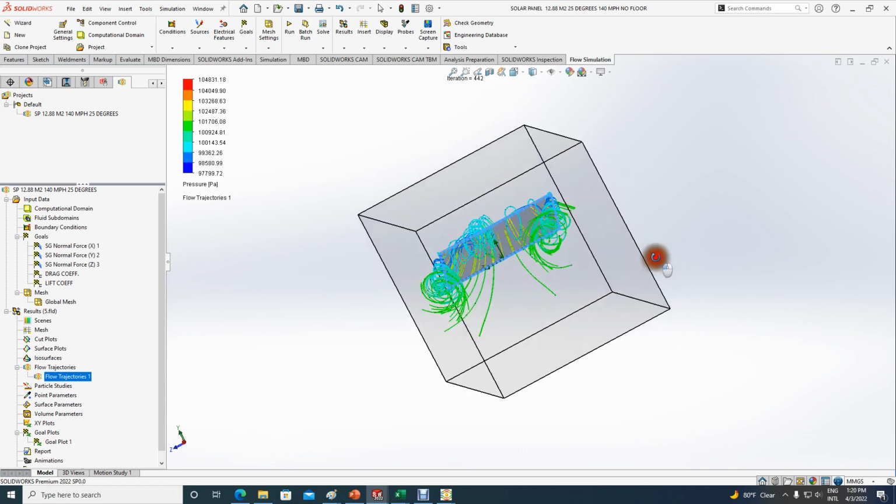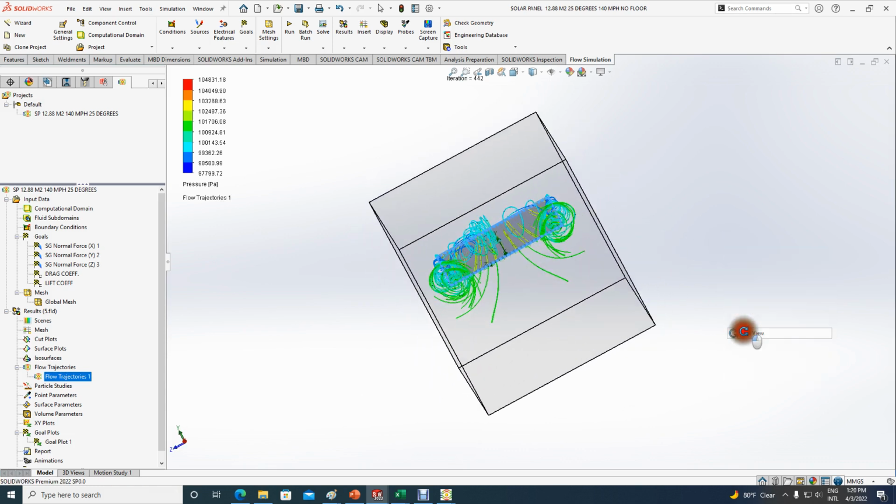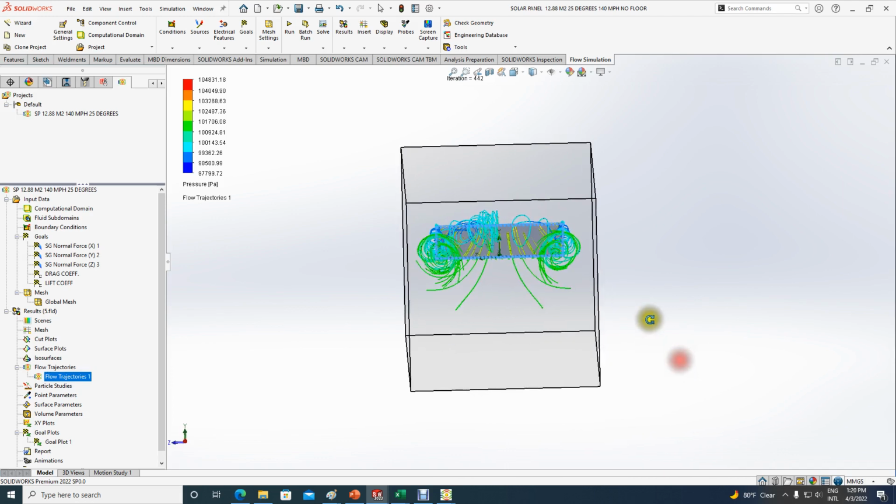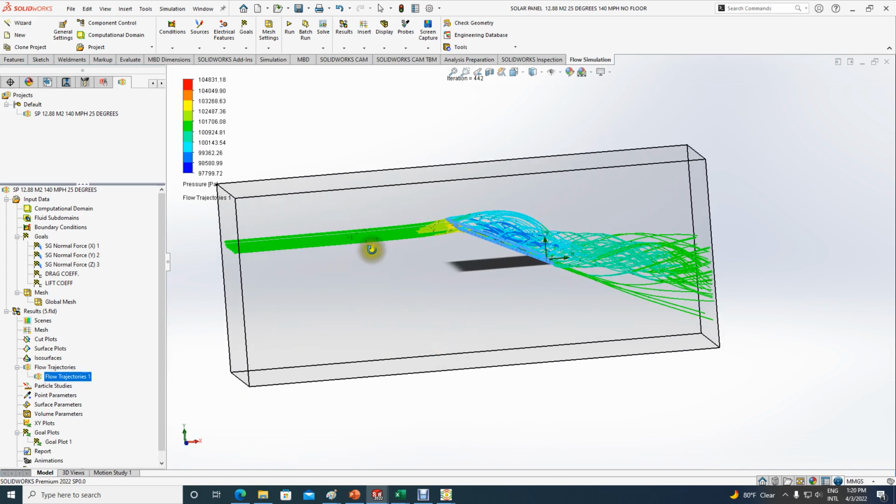You can see the vortex right there as it comes from the back of the solar panel. It looks good. One thing that I might do, rotate again, is to definitely reduce this. Leave the same mesh size in the X direction, but just reduce it. Now that I'm certain that the impact on this area shouldn't be a problem if I reduce that, that would make a lot of sense. That would improve the accuracy of where I want to have more points.